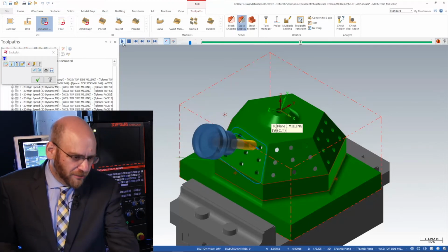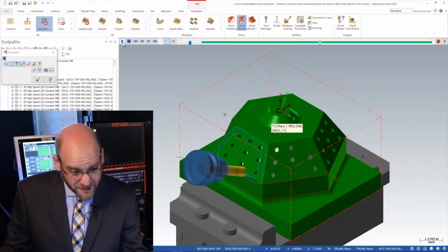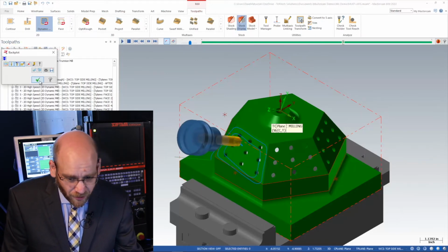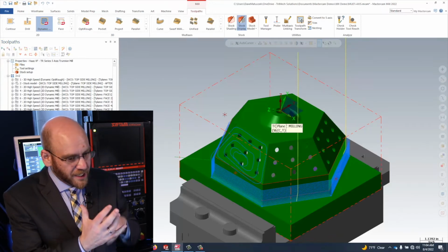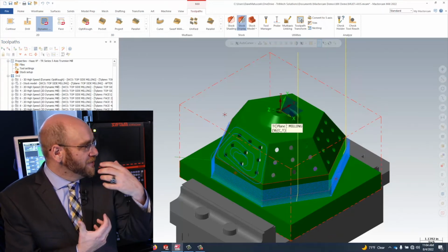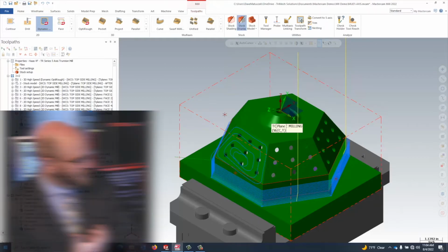And you know what, I could do all these faces, and I did here just for demonstration purposes. I could machine all these holes that exact same way. Make the plane, drill the hole. Index, make the plane, drill the hole. Mastercam gives you yet another option, and that is the curve and drill 5-axis add-on. It's all built in the same drilling toolpath, so there's no need to learn a new toolpath.